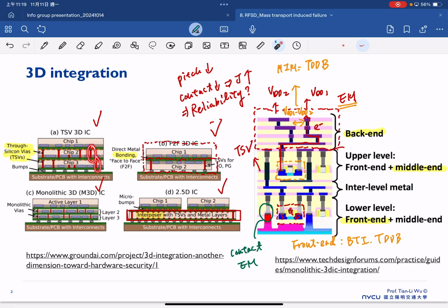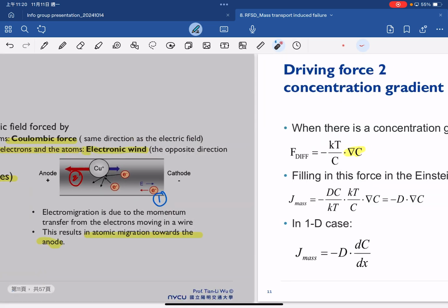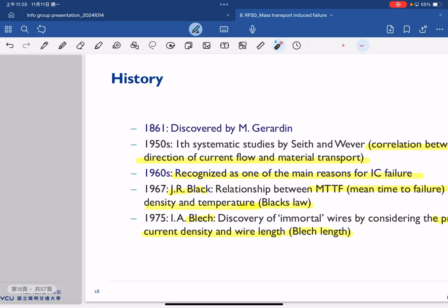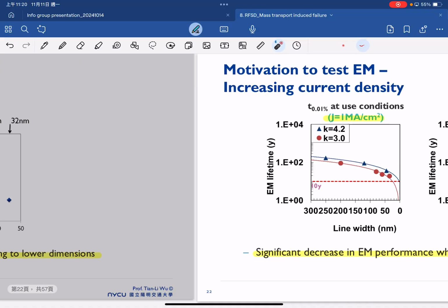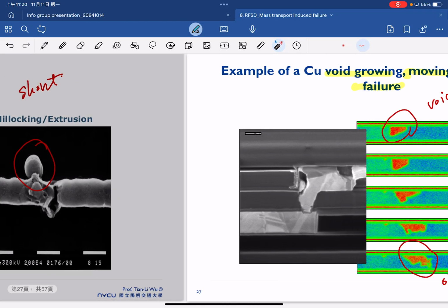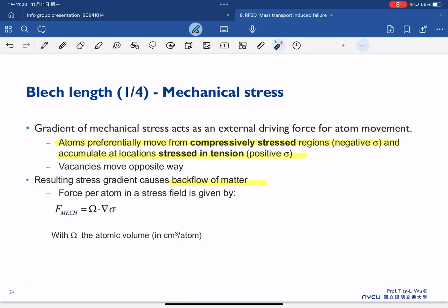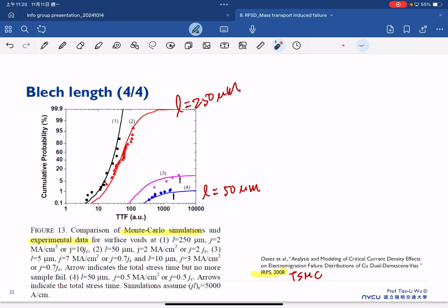Of course, that brings some other challenges. For example, our chip substrate thickness should be below 50 micrometer. That's a little bit complicated, but at least this gives a hint of how we can leverage theoretical understanding to improve our overall reliability. If we can make this below 50 micrometer, we can save our chip from suffering electron migration reliability problems. That's why we have to understand this critical length, because the purpose of reliability is not only understanding and investigation. In the end, we want to propose a strategy to improve device reliability and enhance our chip and product robustness.